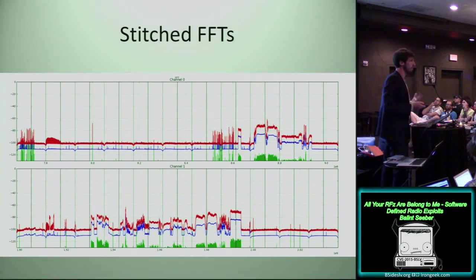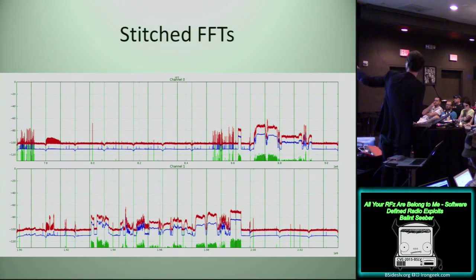So this is just like a generic tool for looking at the radio spectrum, and what's nice is that as you end up doing this sort of sequential scanning, you can store these individual captures, and then you can stitch it into one really, really wideband FFT. So here we're looking at the two regions of the cell spectrum allocated. This is in roughly the 800 megahertz region, and this is in the 1.9 gigahertz region. And you can see that each of these individual sections are one capture.